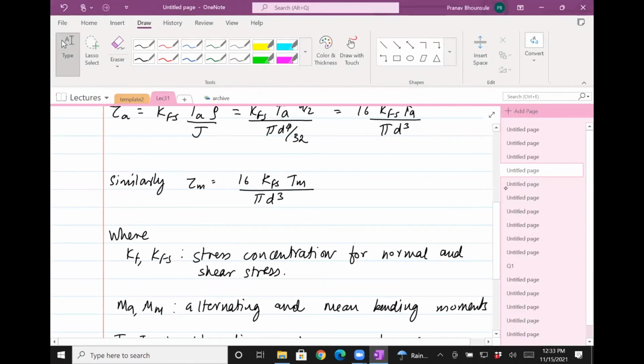So there's a lot of formulas now. We have ductile materials and brittle materials, and we'll ignore brittle materials for a while because we normally design things with ductile materials. Within ductile materials, we have to use a failure criterion: maximum shear stress or distortion energy. We've seen that the maximum shear stress theory is conservative, so distortion energy is much better.